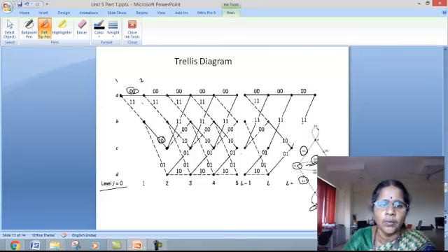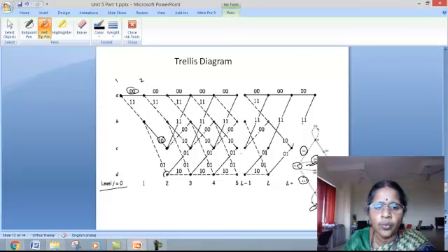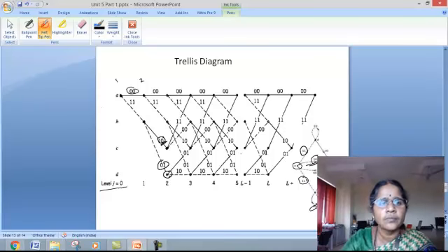This is a second state. Now this is a third state we are talking about. So from state B, you are coming to state D, producing an output of 1. Since the message bit is 1, the dash line is used here to construct the trellis diagram. So from B, input of 0, go to state C with an output 1, 0. From B, the next state is D, producing an output of 0, 1 when an input is 1.